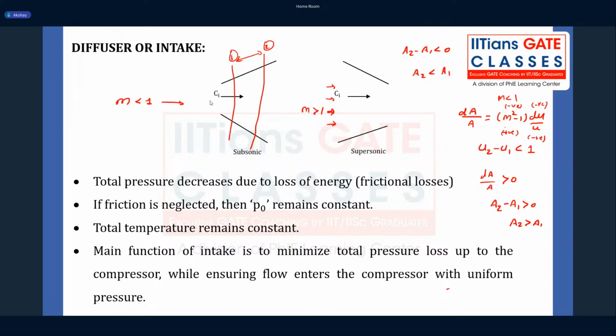And from the thermodynamic point of view, we assume the process is adiabatic, right? When we analyze a flow through ducts, that means there is no work transfer and no heat transfer across the boundaries. So we assume all these things while modeling the flow. But in realistic flows, it is not the case, because friction is inherent. Whenever I have a solid body, the flow has to see the solid boundaries, so we know that there is a no slip condition.